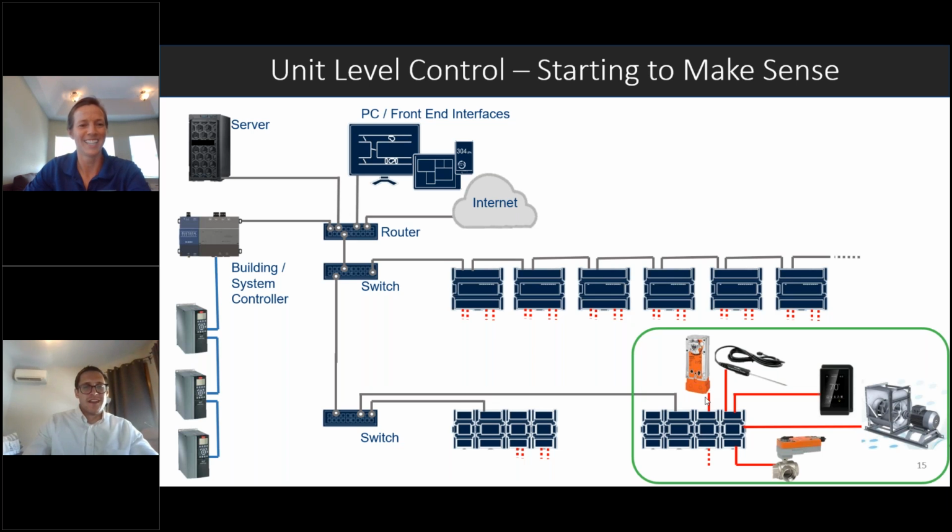So we're going to immediately knock out the over Ethernet one. That is definitely not an option you want to look at. You can run into a lot of issues with that older style communication. It was only around for a few years before BACnet IP took over. Now comparing BACnet MSTP and BACnet over IP, for any new installation, you should be using BACnet IP. There's no questions asked about that.